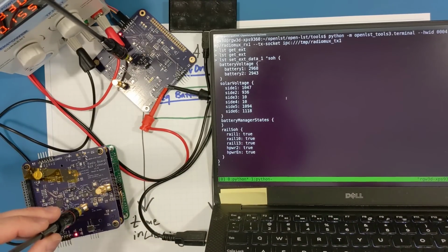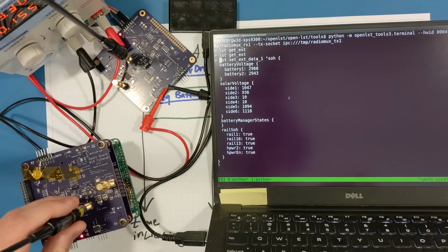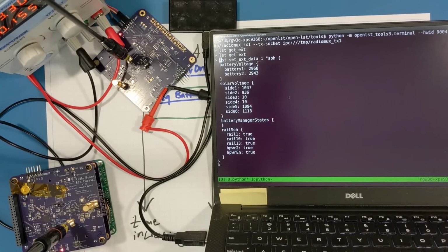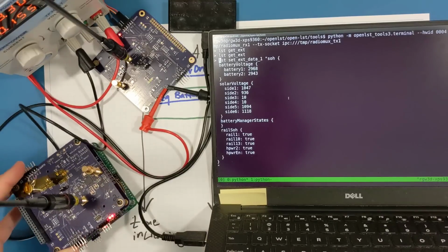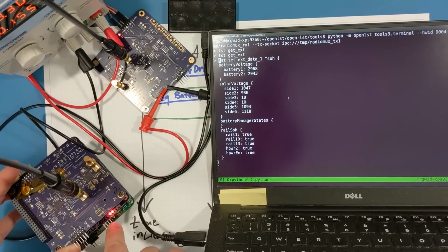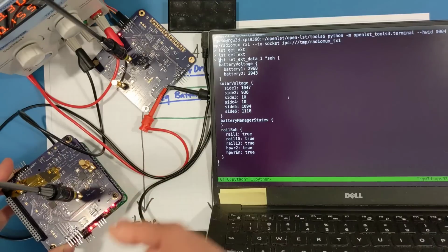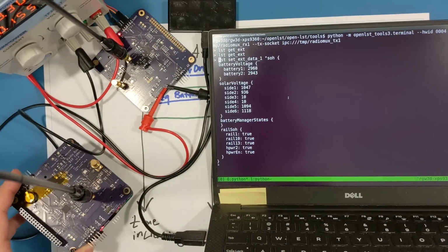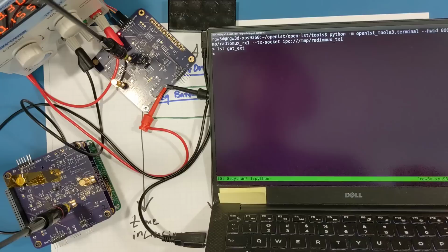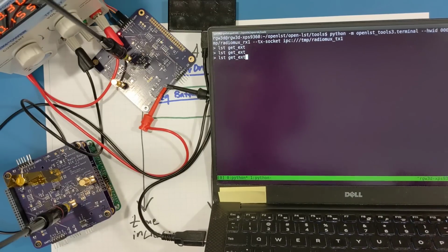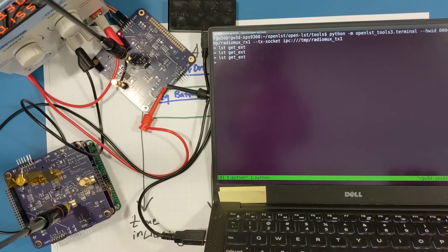And just to prove that this is actually communicating with this guy, we can turn off power and run the command again, and we'll see that nothing happens. Alright, so I've turned off this radio, and I did that by just disconnecting one of the battery supplies, and the avionics board knows that if one of the batteries is gone, it should turn off the radio, so the radio is off. Rerunning the command will just continually hang as there is nothing to get a signal back from.